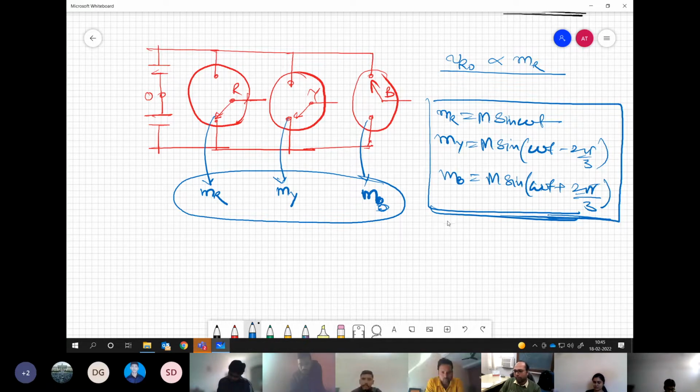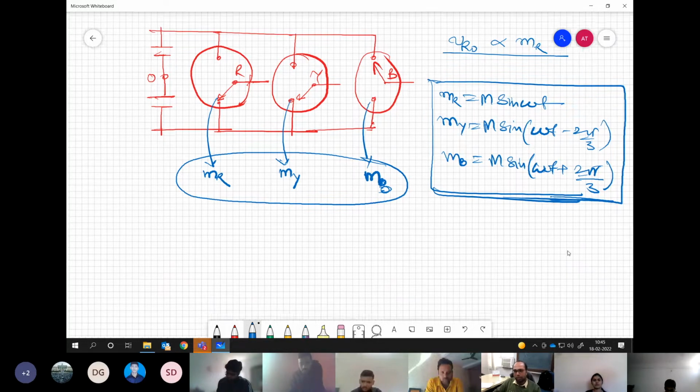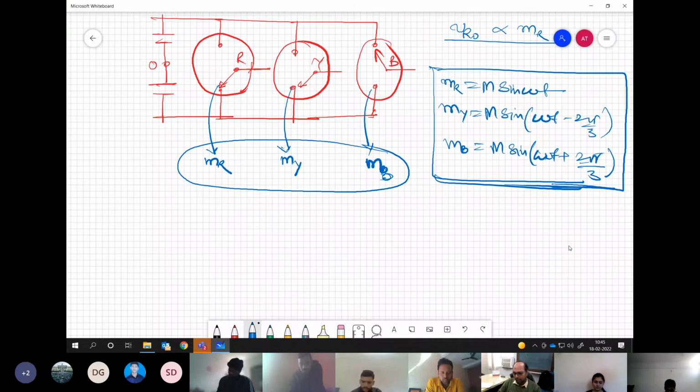Similarly, you may have a 5-phase, 9-phase, any converter. You can give the appropriate balanced modulating signals and you can generate the correct output. Now, for all this, we should generally have the same carrier for this comparison. Understanding my point?